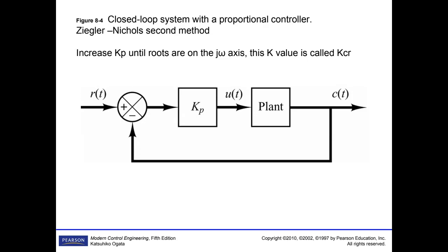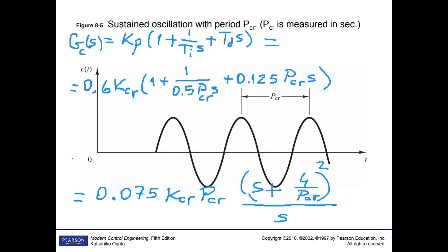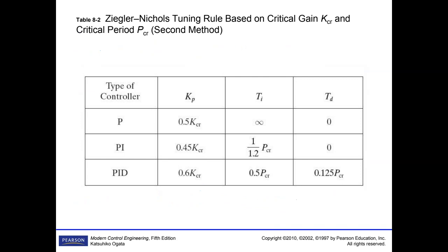As long as you put KCR, you can see that when you put KCR, you obtain the KCR value. Then delta is the denominator of the transfer function, and if you put KCR equal to 30, you obtain omega.